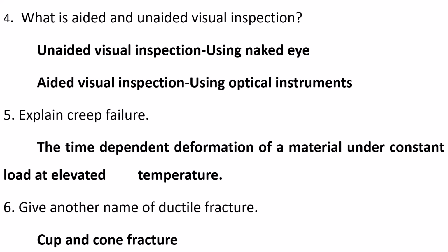Fifth question, explain creep failure. The time-dependent deformation of a material under constant load at elevated temperature is called creep failure. That is, a creep failure takes place at elevated temperature over a long time, or a certain duration of time is required for the change in dimension or deformation. That is called creep failure.